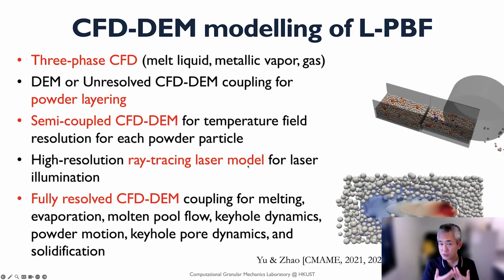And then to resolve the temperature field, we developed a so-called semi-coupled CFD-DEM. I will show what a semi-coupled is. Don't confuse this with semi-resolved, which is different here. Okay, and it's also important to resolve the laser source model more accurately. So we developed a high-resolution ray tracing laser model for the laser illumination, because different laser illumination models will cause different energy absorption, and you can generate quite different results here.